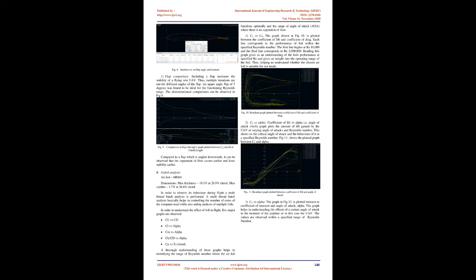The next step is to decide a suitable taper ratio, which consequentially gives the length of the tip chord. This ratio is selected based on the function of the UAV, the type of wing it utilizes, its operating range of Reynolds number and the highest achievable velocity. Accordingly we have chosen a low taper ratio as we have determined the UAV to be a glider type, utilizing a flying wing, operating at low Reynolds number with a maximum achievable velocity of 10 m/s. A taper ratio is the ratio between the root chord and the tip chord of the wing.